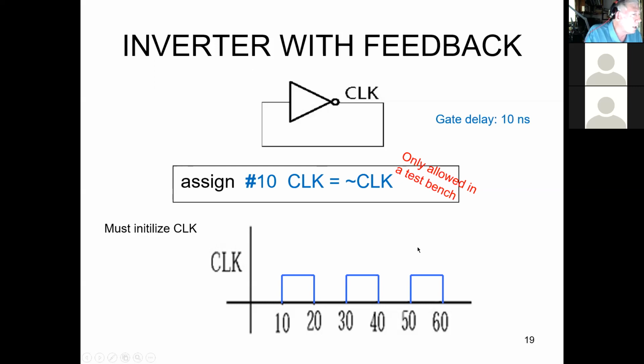And we do use the clock a lot because Vivado and the Xilinx chips like you to have a clock, even though you might not need one if you're just doing a combinational device. But still, I recommend you use a clock pretty much for almost everything, because if you don't, sometimes you'll get a whole lot more convoluted hardware than if you have a clock.